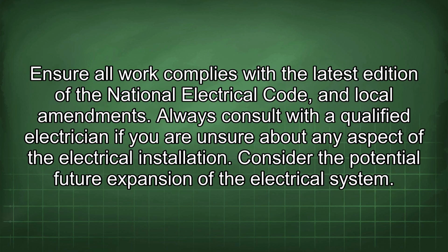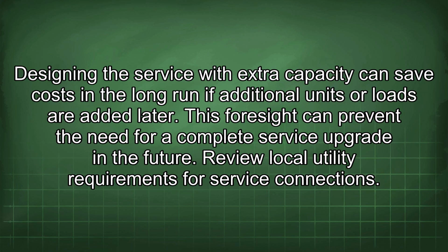Ensure all work complies with the latest edition of the National Electrical Code and local amendments. Always consult with a qualified electrician if you are unsure about any aspect of the electrical installation. Consider the potential future expansion of the electrical system. Designing the service with extra capacity can save costs in the long run if additional units or loads are added later. This foresight can prevent the need for a complete service upgrade in the future.